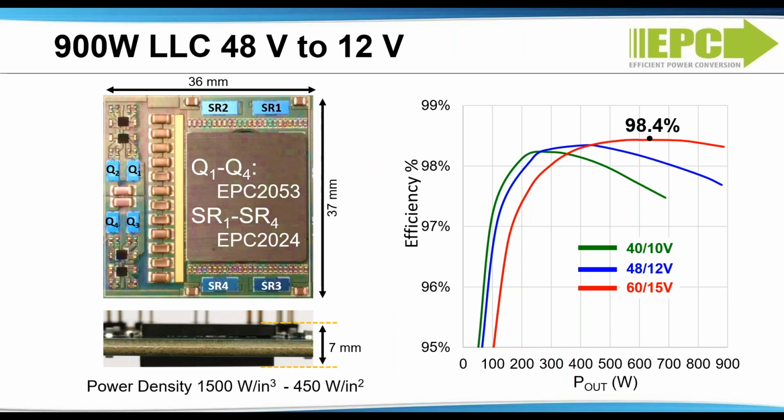Even though the 48 volt to 12 volt front end conversion is lower efficiency than 48 volt to around 6 volts, it's still predominant for servers due to legacy loads that are powered from 12 volts. The latest servers and AI solutions are already requiring input power of around 200 kilowatts and even more. This requirement puts the switch cap topology at a severe disadvantage since switch cap solutions are really not good above 600 watts. They require a significantly larger footprint and have a higher cost.